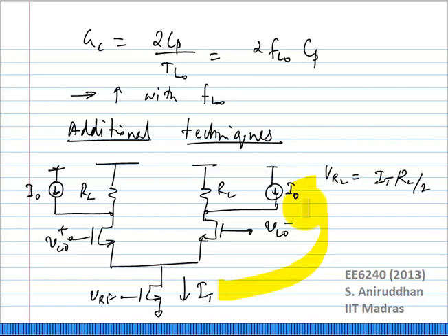Anything about current sources? Current source noise will come in. But if it's just a simple PMOS transistor, what would you try to do to reduce the noise? For a current source, if you want to optimize the noise, you should reduce the GM, right? Okay. If you try to reduce the GM, what happens to the device size and current?